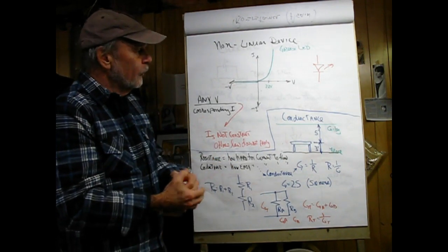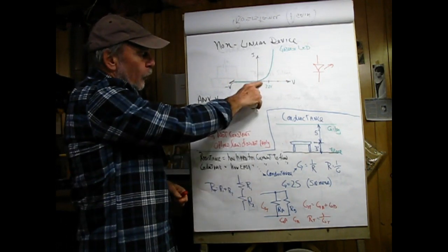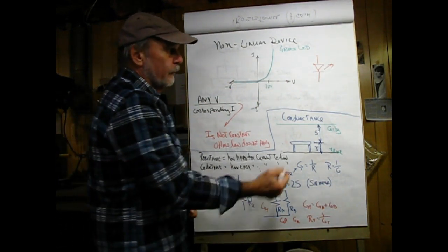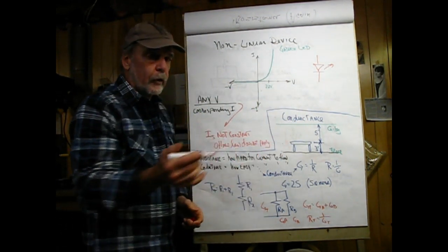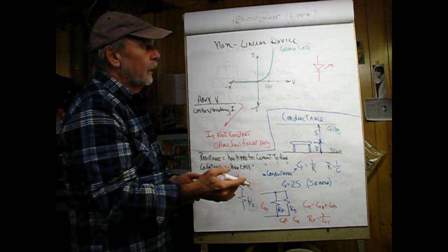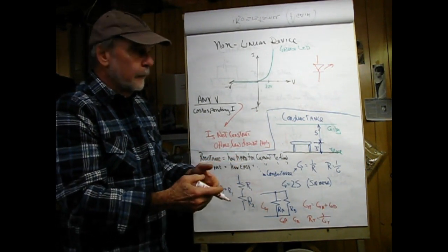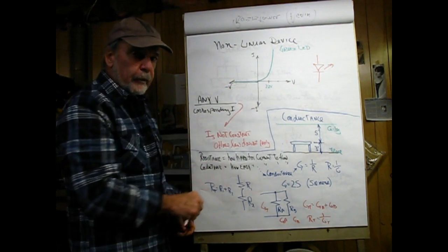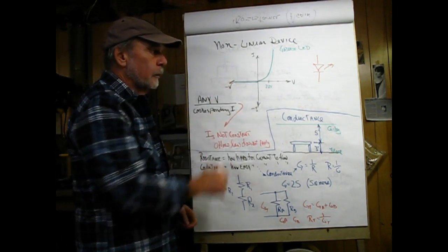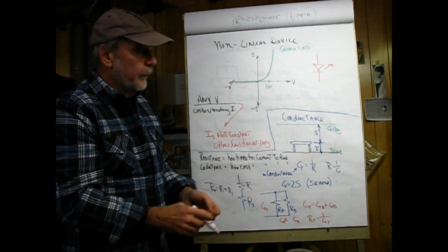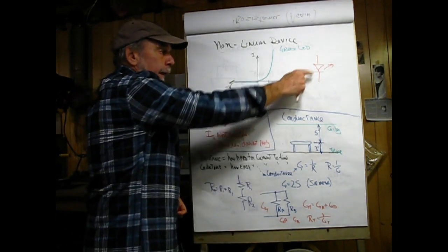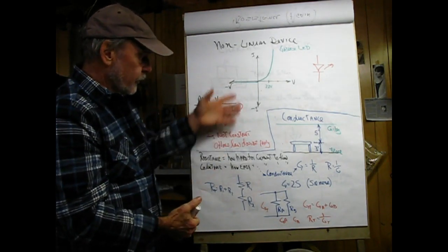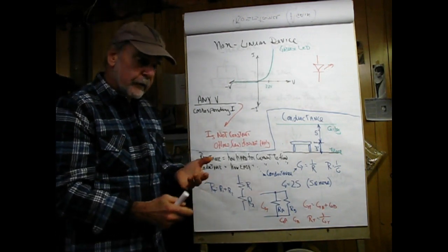Okay, anyway, so that's an example of a nonlinear device. And note that if we make V negative, we have this leakage current which is flowing backwards. So if the current flow, I'm not going to draw it because there are two kinds of current flows here, is flowing with the arrow, it'll emit light. If it's trying to flow backward through this, there'll be a little bit of leakage, but it will not light, until you get over to here somewhere, where you break the thing down. And it just basically arcs, if you will, through the gallium arsenide that thing is made from. Okay, so that's an example where Ohm's law would not apply, and let's move on to another concept here.